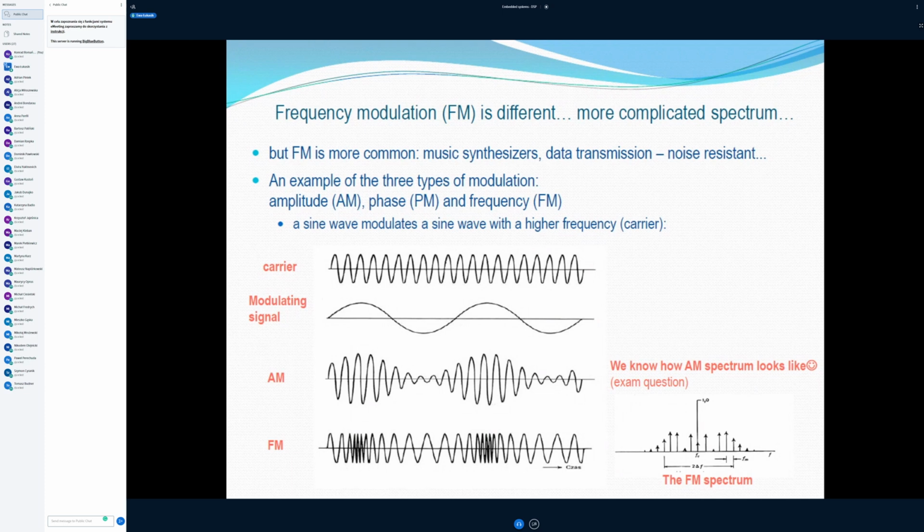And what is very interesting, we may observe a similar spectrum if the modulating function is in the shape of a rectangular. How can we explain that? Well, the rectangular function has harmonics that have frequencies being multiples of a fundamental frequency.